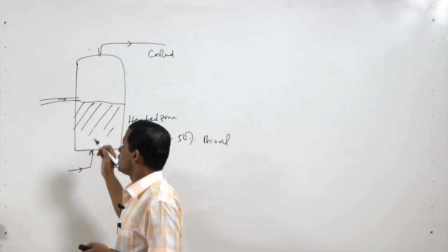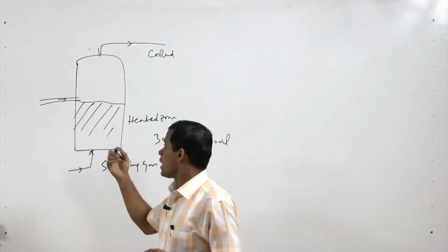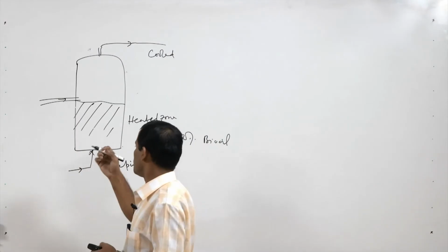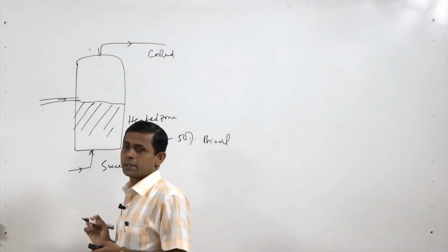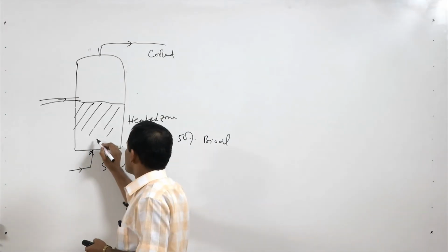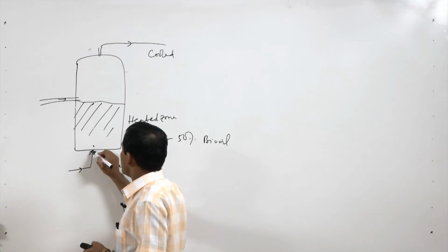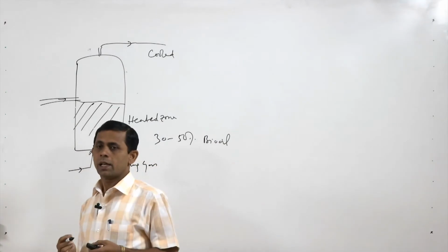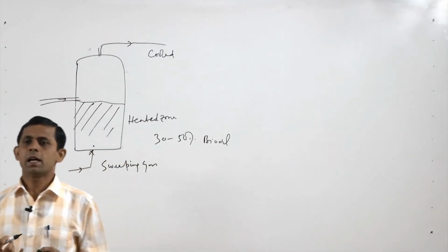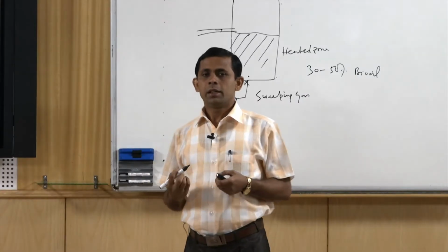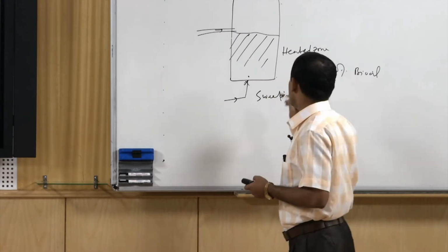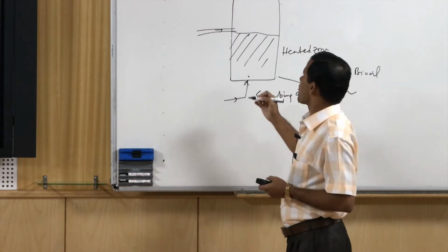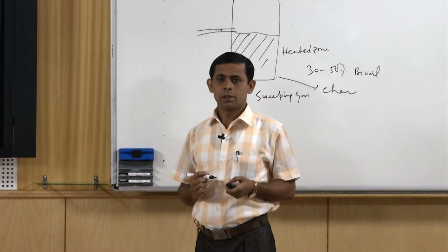Sand is used there so that it has a high heat transfer coefficient, and so the rate of heat transfer is more in those reactors, but here the rate of heat transfer is less, and basically gas to solid heat transfer takes place. There is no solid to solid heat transfer, that is why the time requirement is higher, and residence time is higher. As a result, the char production is also high here, more char is produced and less bio oil is produced.